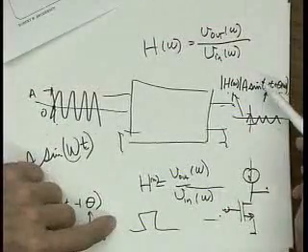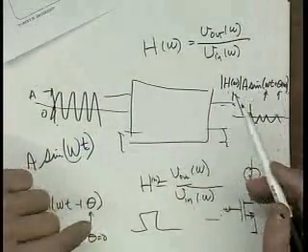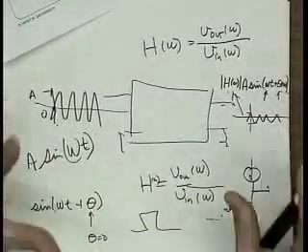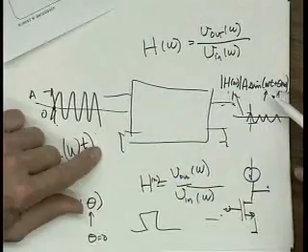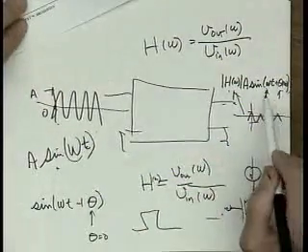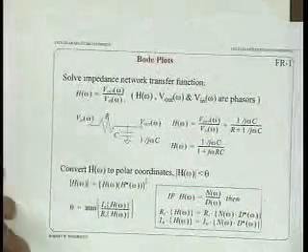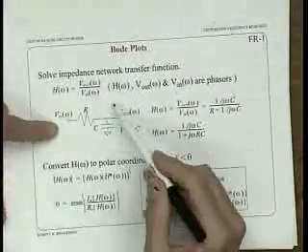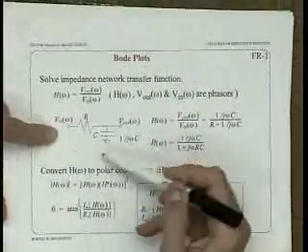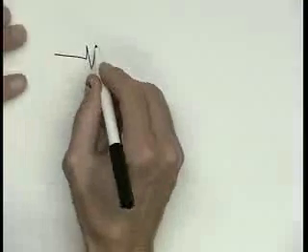It's a fact. So sine waves are very special. They're basically eigenfunctions of the differential equations which describe these linear systems. Okay, so it's a really fundamental reason why sine waves are so important to us. Now we'll just treat it very pragmatically and know that if this goes in, this comes out, and we'll just worry about it. But it's really a very fundamental difference, okay, from any other waveform. Okay, so let's calculate this transfer function, V out of omega versus V in of omega, for a simple RC network. Okay, let me just go to drawing this.